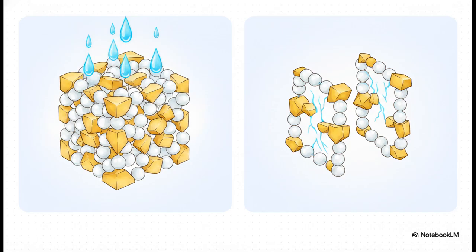Because of this, hard wheats require complex chemical manipulation through targeted moisture. We use moisture to precisely weaken that tight protein bond, allowing the mechanical systems to fracture the kernel properly without blowing the entire structure into dust.